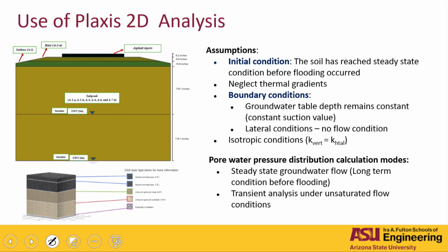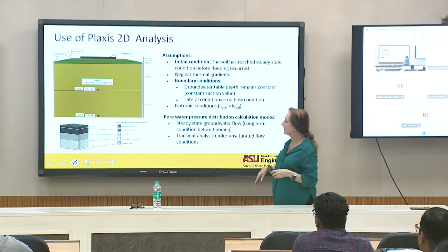So we got an asphalt layer. We got a granular base material. Are you guys familiar with the AASHTO classification A1A? Okay, AASHTO classification A1A is pretty much a well-graded gravel, something like that. There are some pavement engineers in here, better than me. So I got an A1A soil for the base, and I got an A3 soil for the subbase. An A3 soil is a poorly graded sandy material, which is very good for subbase materials.